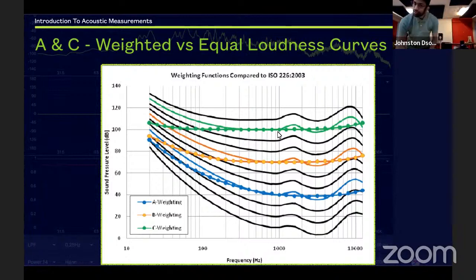Especially when you're doing live sound, where we are playing our system at about 100 dB SPL approximately for 2.5 hours, and on average, not always at 100 SPL, we are more worried about the C weighted scale. If we are only looking at the A weighted scale at 100 dB SPL, it's not a right representation.